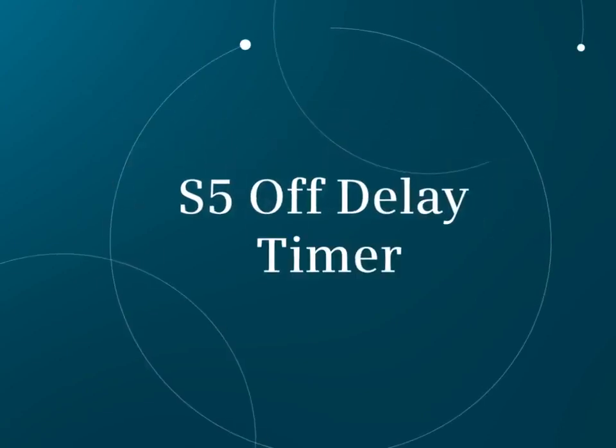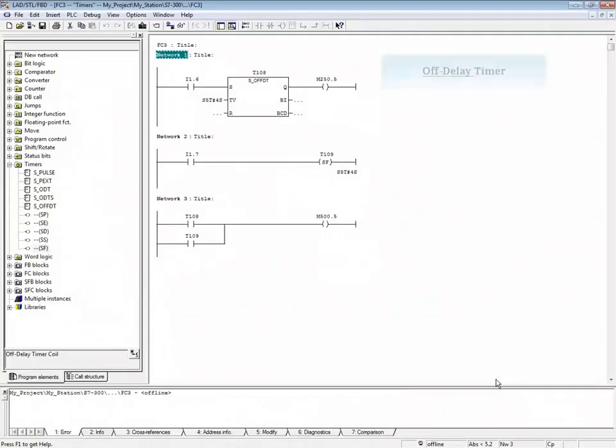In this video, you'll see the off-delay timer and off-delay timer coil. Network 1 has the off-delay timer, and Network 2 has the off-delay timer coil. The off-delay timer starts on the trailing edge of a 1 to 0 transition. The input is true before the timer starts. When the input transitions from 1 to 0, the timer begins timing down.